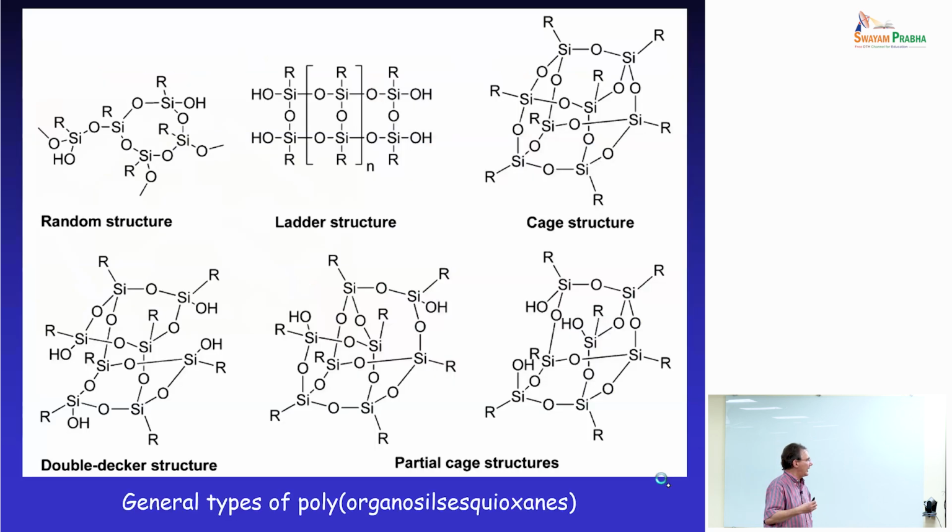So in order to avoid a lot of losses, you need to avoid using preceramic polymers that have a linear chain, because a linear chain during pyrolysis will break down into shorter chains, which tend to evaporate. So you will start from 100 grams of your shaped polymer, and after pyrolysis, you will end up with 7 grams or 5 grams of your ceramic material. So it doesn't make sense to volatilize 93% or 95% of your material.